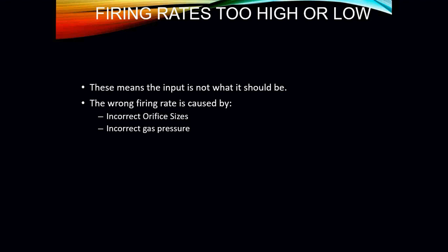Now, if the firing rates are too high or too low, this means that the input is not where it should be. This could be caused by incorrect orifice sizing or incorrect gas pressure. Look at your manufacturer's literature, look at the nameplate to see what your pressure should be and what the actual orifice size should be.